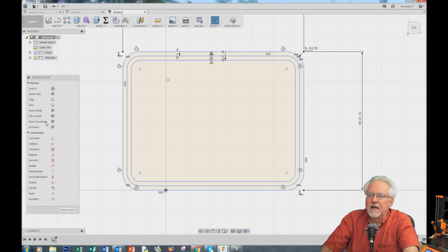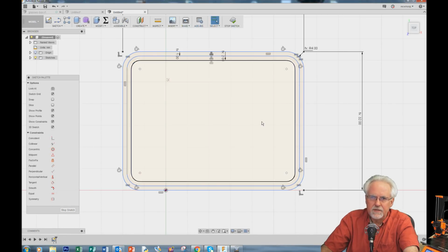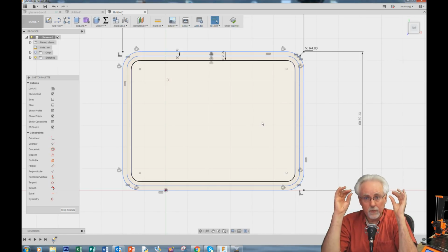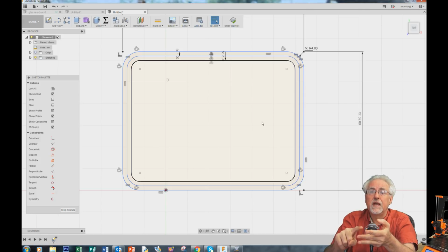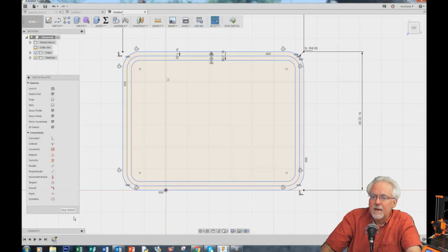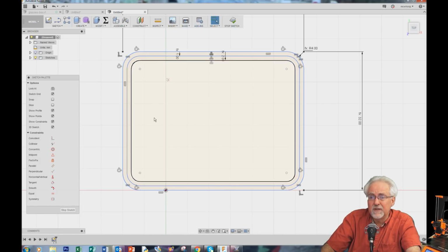What's one thing that we don't like? This thing is jumping around. Why is it jumping around? Okay, what do we think? We think deliberately about dimensions. Did a good job there. Parameters, did a good job there. Position and constraints. What happened? When I rounded this corner, the constraint that kept the corner of this structure pinned to the origin, that point disappeared, so the constraint disappeared with it.